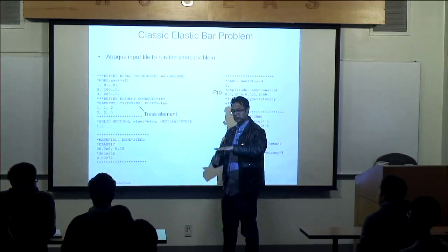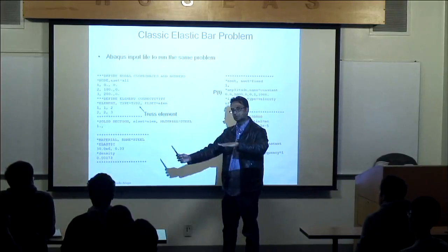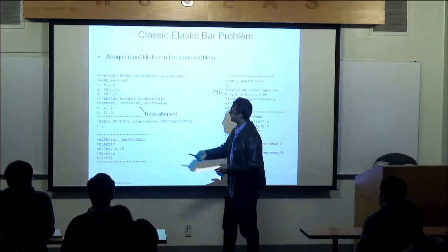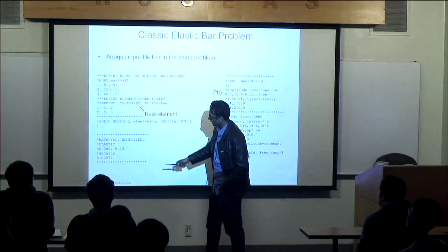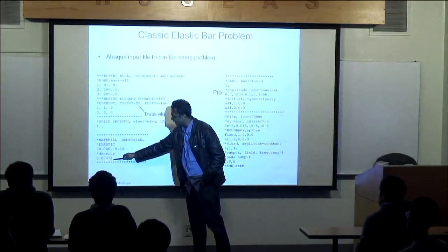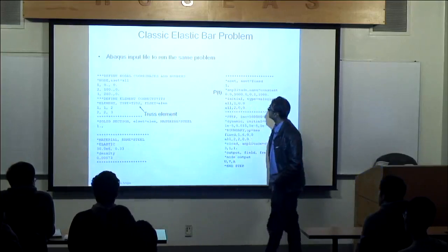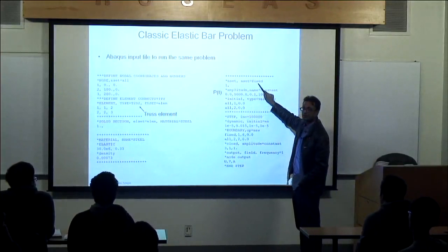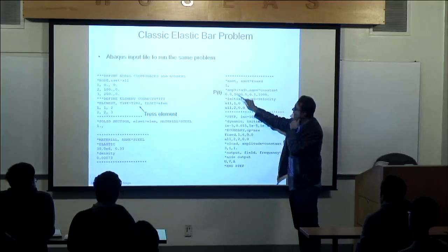So I fixed the degree of freedom going vertically so that it only moves axially, because we're looking at a truss. I'm just looking at an axial bar. So I used 2 elements. The length is 200. I put a density of 0.073, modulus 36, Poisson ratio 0.33. Here, I set the left-hand side fixed, because it's clamped on the left-hand side, node 1.